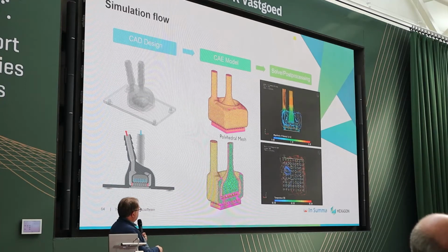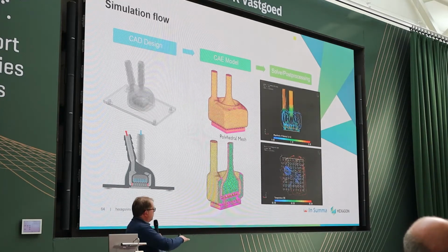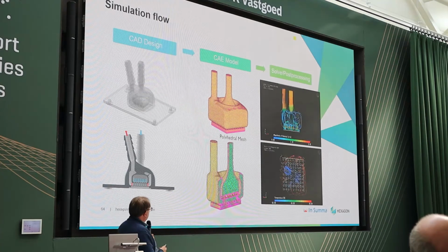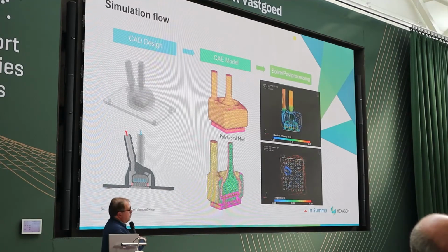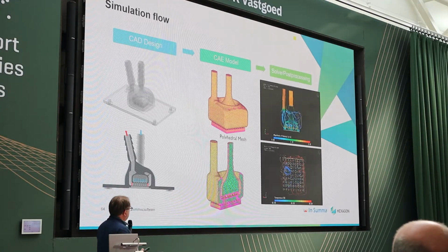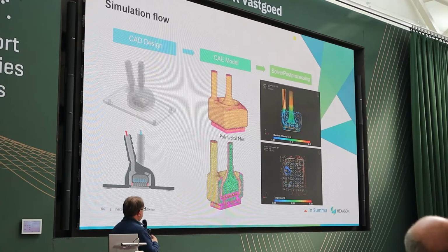The objective was to redesign the structure, maximizing the heat transfer and also trying to have cooling all over the chip, not very localized in the center, for example. Also, the corner areas should be cooled as well as possible, while minimizing the pressure drop. The optimization is still done in a kind of manual way, so it's not like an Odyssey-based optimization. Maybe that's something that can be useful in the future.